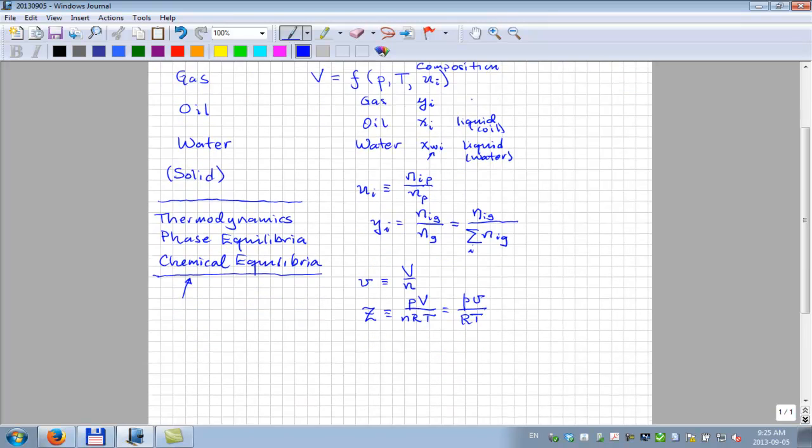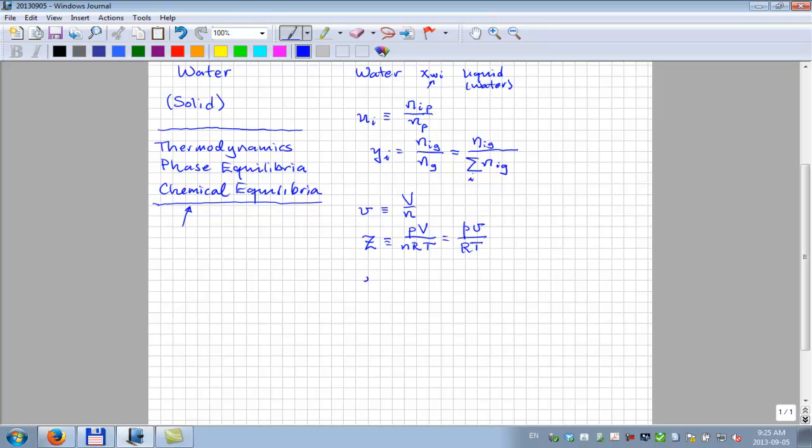So these are two terms that we've used for volumetric quantities. And the last one, which is really important for engineering applications, is the mass density, because the mass density, when multiplied by the acceleration due to gravity, is what causes pressure increase as you go down in a column of water, gas, oil, whatever you have. So the pressure is tightly coupled in a static column of fluid to the mass density, and that is a very important engineering quantity for really any engineering field.